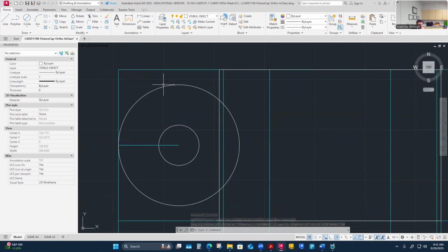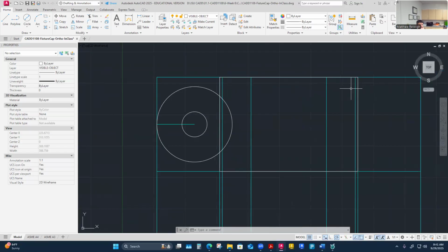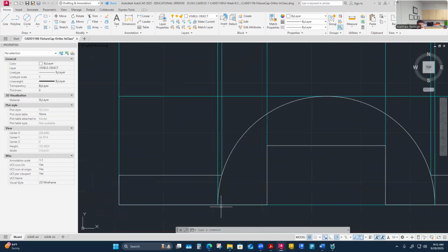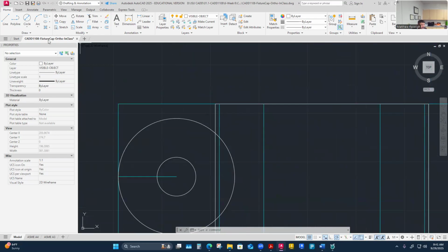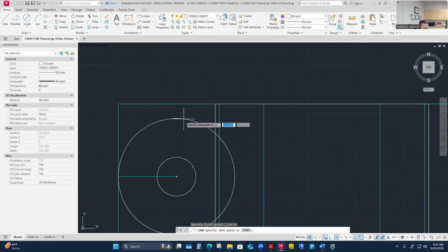And then what it has is it would be tangent from that radius to this point here, or actually clear to this point. I'm going to see the ear as this line that's a little bit less than the actual diameter of the cylindrical part. My ear is going to terminate there just because of what's going on here in the front view. This is going to be a visible line that I see, which is slightly less than the full diameter. So that's where I'm going to draw my line, clear to there. So I'm looking for a tangent here. I could do quadrant, yes, but really what I'm looking for is a tangent line on this.